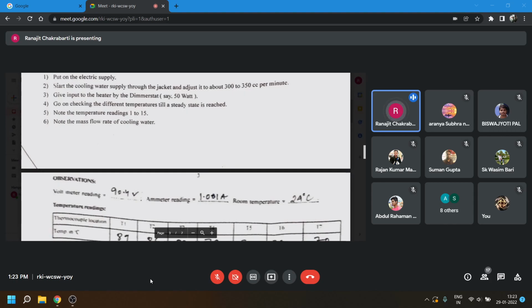When will internal heat generation come? If you have a metal rod which is made of uranium, and you are heating up one end of the rod and inside the rod also there is some nuclear fission going on, then there is a heat generation. Then the boundary condition will be different. Then the equation will be different.